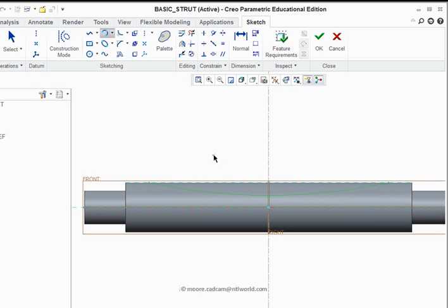And now need to put in some dimensions, so I get the dimensioning tool. From one end to the other end, if the arc wants to be 60, so I'm just center clicking to do that. That is automatically centered about the center line that I drew in.